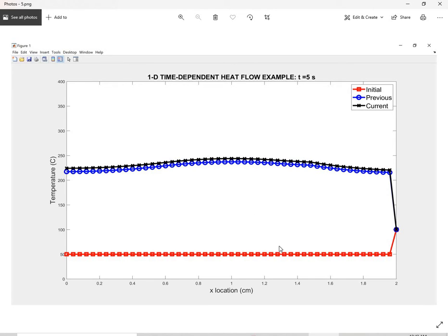This here is my temperature distribution at half the time, and that is at t equals 5 seconds. So here are the 4 different sections, and the material properties of each one lead to faster temperature rises in certain areas. The second section, from around x equals 0.6 to approximately x equals 1.3, we can see that it heats up faster than the rest of the rod because of Q equals 1000 watts per meter applied to that section.